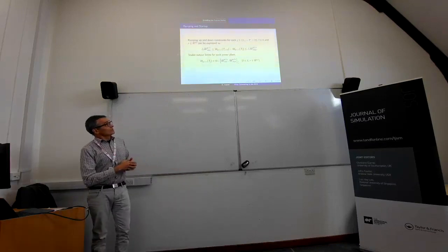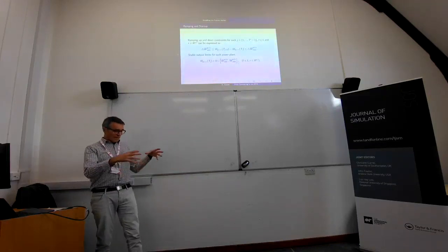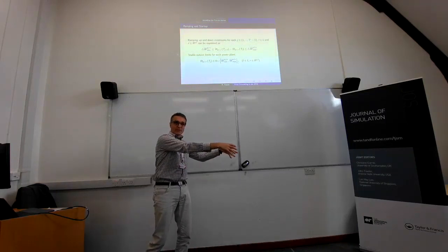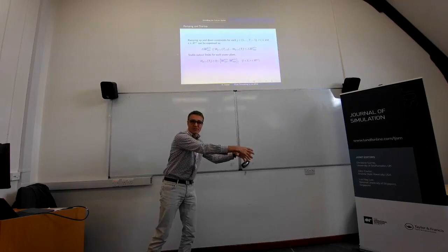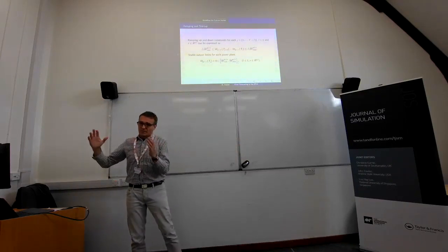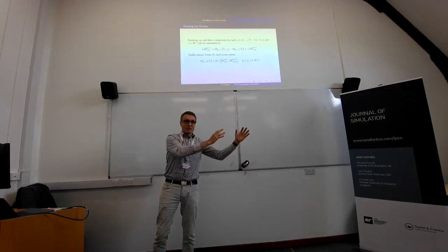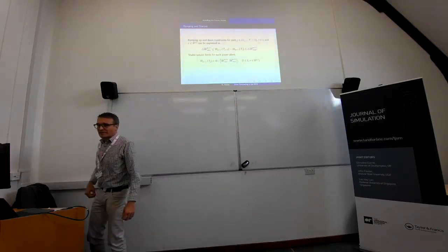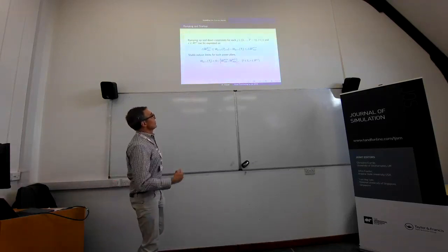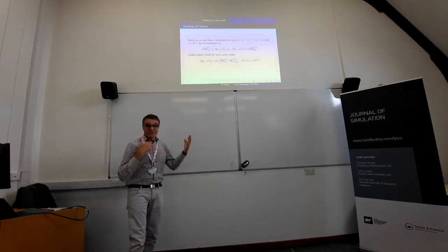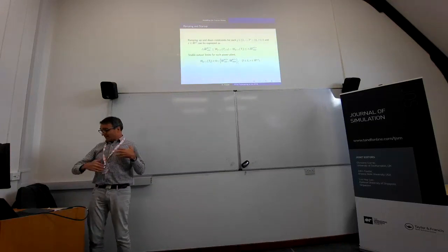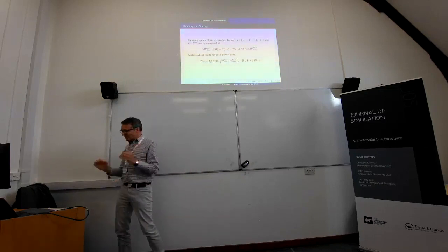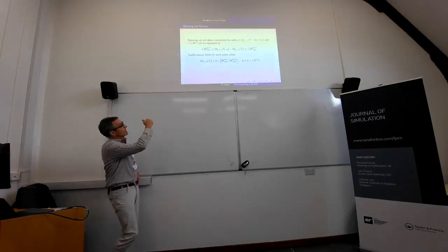And then there's a further complication: if you plan the delivery into a half-an-hour slot, then that's coupled with what the delivery in the next half-hour slot is, because a power plant can't ramp up or ramp down production at arbitrary speed. So again, every power plant has its own upper and lower bounds on the ramping speed, and you need to find out what these are for each power plant. So you need these physical characteristics, and then the stable output limits.